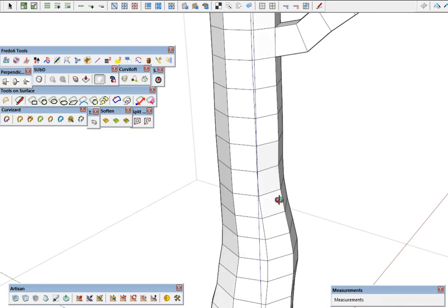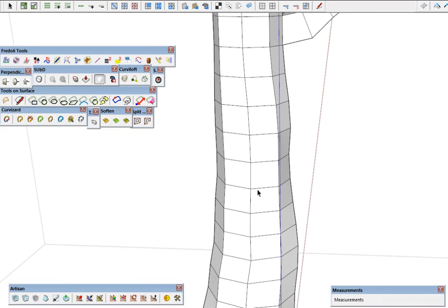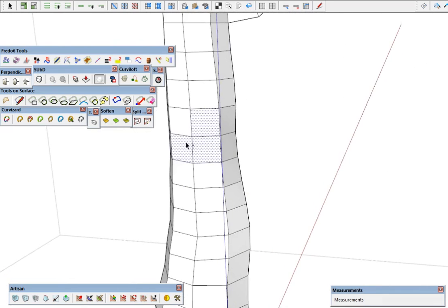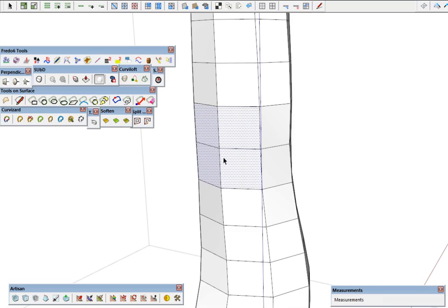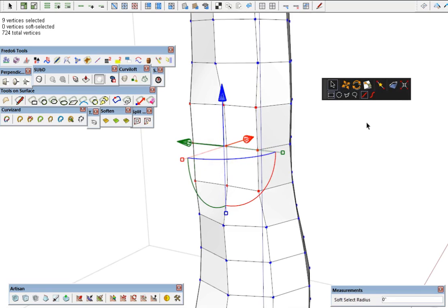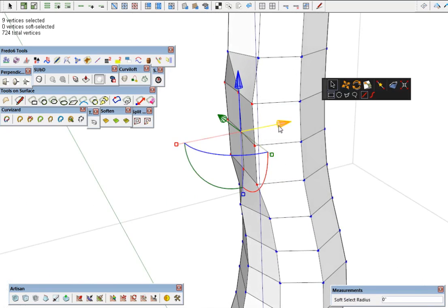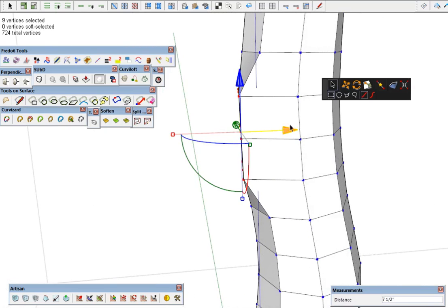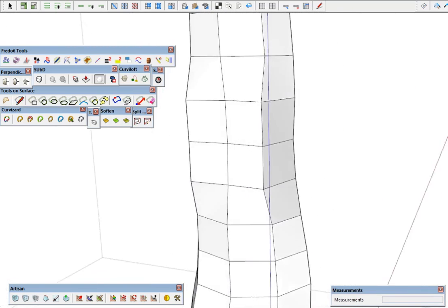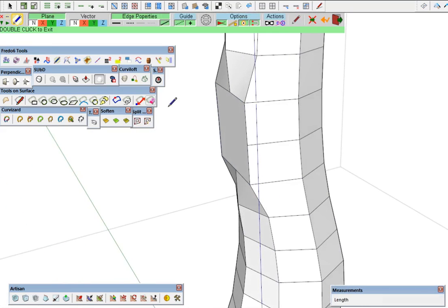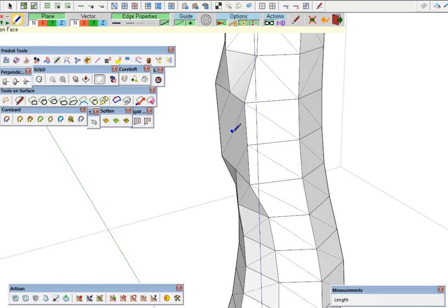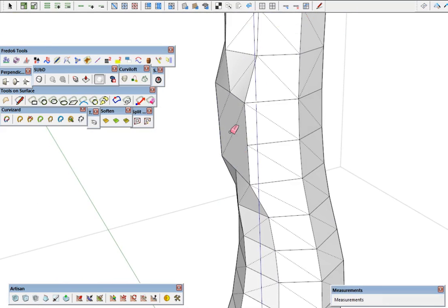So the other thing I wanted to mention is you can also, if you wanted to make a really big branch, you can also do that with 4 of these here. And you would have to, either with vertex tools, you could go make planar with those, pull that out, delete those edges there, get in there with draw along, and delete those hidden edges first.